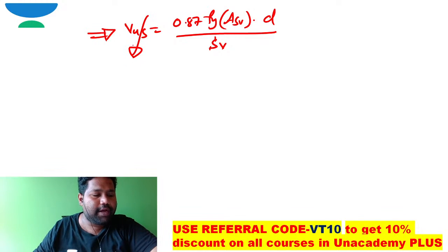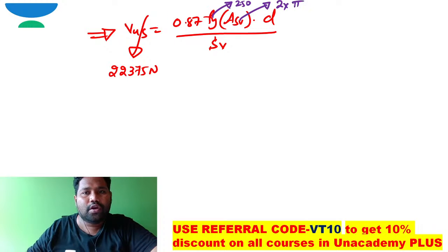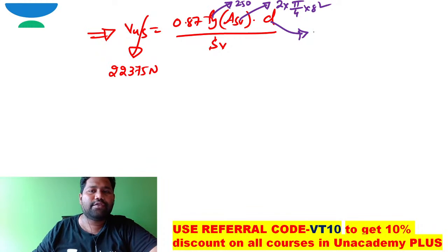It is 22.375, so in terms of newtons, it is 22375 Newton. Coming to fy, fy is Fe 250, no? It is 250. Asv is 2 into pi by 4 into 8 square. Effective depth d is 450 millimeter. So the one and only unknown is Sv.